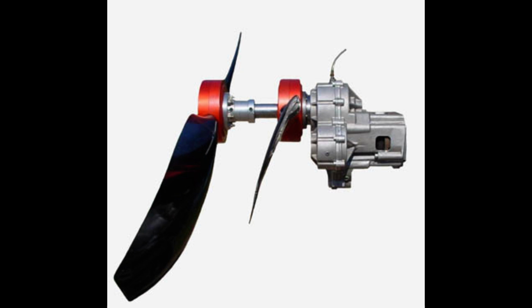A centrifugal clutch is very useful in a 2-stroke engine because it allows the engine to idle at a lower speed without the load of the propeller. Otherwise, 2-stroke engines can generate a great deal of vibration at low RPM when loaded. As the engine speeds up, the centrifugal clutch engages and smoothly starts the propeller spinning. When the engine is brought back to idle, the clutch disengages and allows the engine to idle smoothly again. The propeller stops when on the ground and windmills when flying.